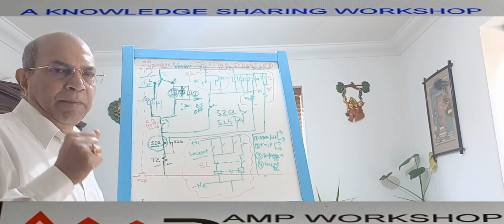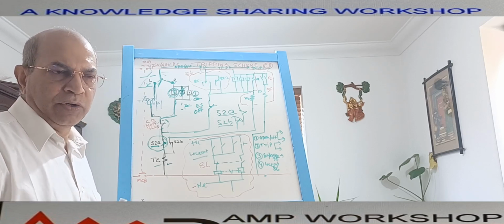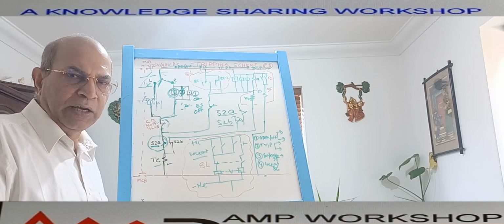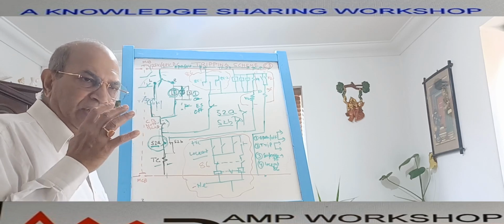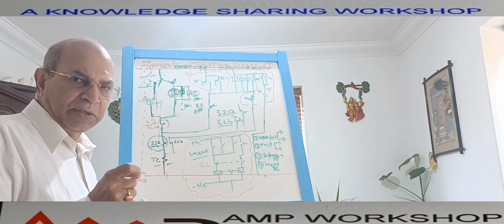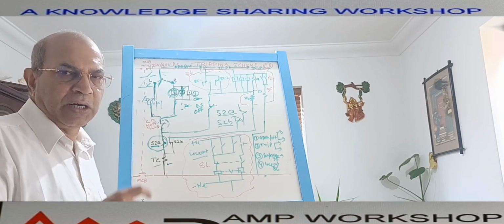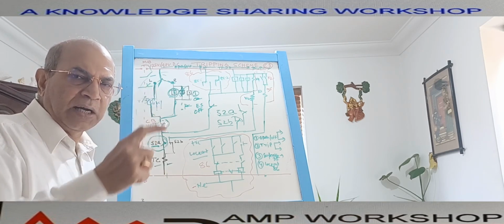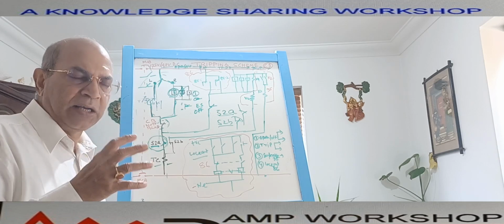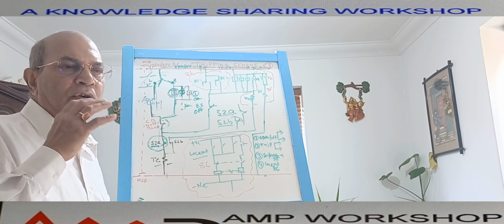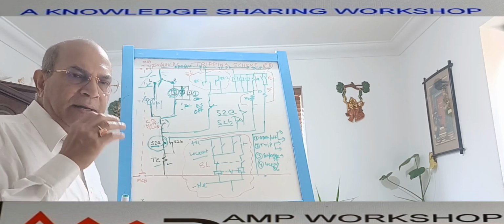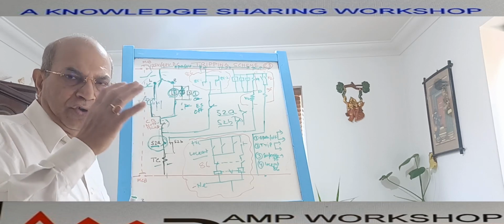Nowadays we have a digital type protection relay. Nowadays we do not use an electromechanical relay. All the relays are numerical relays. So to the digital relay we give the CT supply and VT supply, and the digital relay has a program. It can sense the current, then compare it against the set current value. The relay will operate, and the relay has multiple output relays.